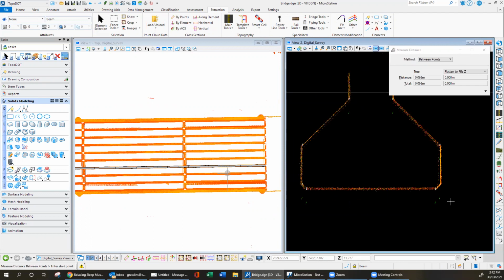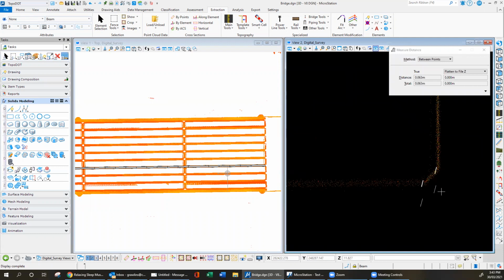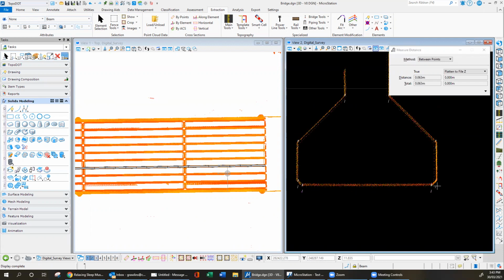63 millimeters of doming, and there is a little bit of bend to the right in this section as well. And finally, we'll compare them against the other ones that were done with the drape line. And again, the drape line ones here are quite significantly away from where it was. We would have had to do the QA/QC on each one of those vertices much more detailed to get that right.